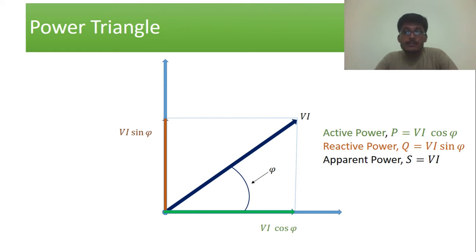Again, if the power factor or the cos phi value is very high, then for supplying the same amount of real power, the current flowing through the circuit will be less. And when the current is becoming less, then mind students, the I square losses and several other losses are getting reduced. Okay. So that is the importance of improving the power factor.